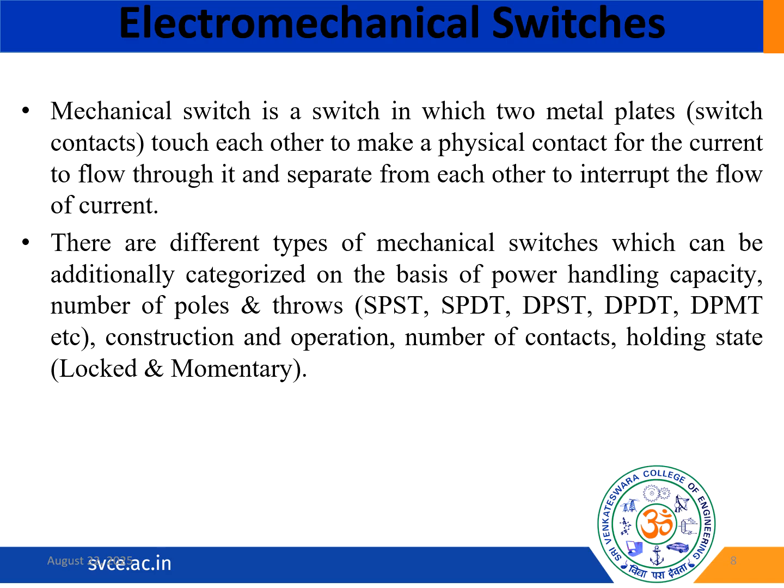So the actuation and construction includes toggle, push buttons, rotary, and more. And there are a number of contacts, which can influence switching complexity and redundancy. And we also have holding state. Holding state can be considered as latched or momentary. Latched maintains its position until it is manually changed. Momentary returns to default state after release.